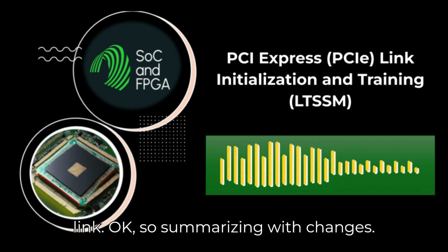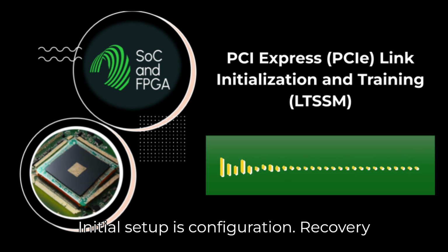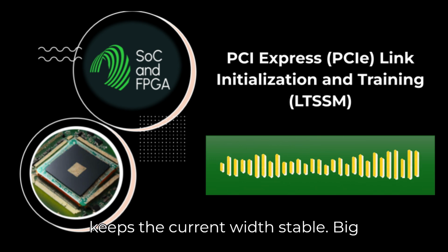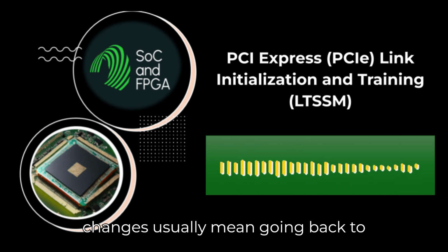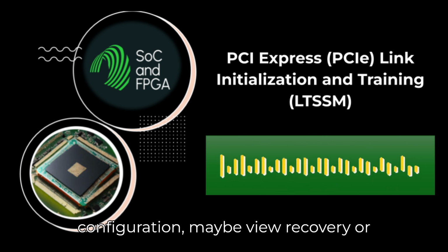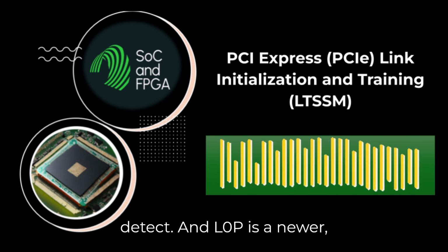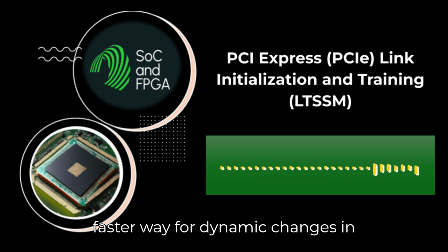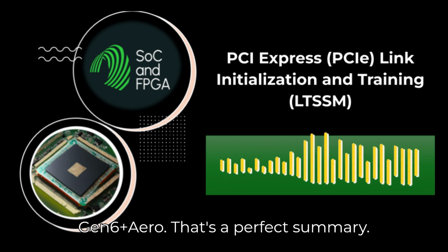Okay, so summarizing width changes. Initial setup is configuration. Recovery keeps the current width stable. Big changes usually mean going back to configuration, maybe via recovery or detect. And L0p is a newer, faster way for dynamic changes in Gen 6 plus. That's a perfect summary. Great.